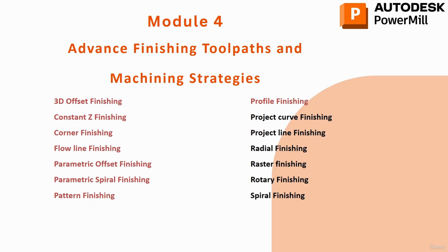In pattern finishing, the cutting tool just follows the curve, either a 2D curve or a 3D curve. But the only difference with profile finishing is that the cutting tool will just follow the surface which you have selected, either the inner side or the outer side. And the surface can be a 2D surface or a 3D surface. So it just follows the profile only. So let's get to the profile finishing operation. Very simple. Let's get started.